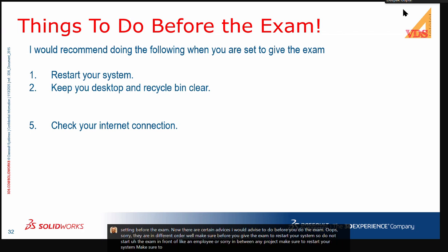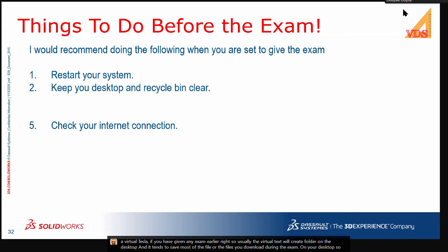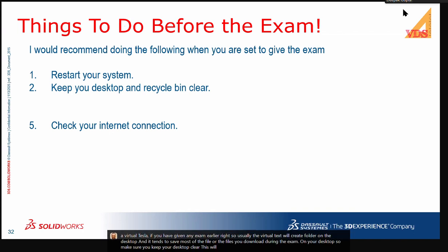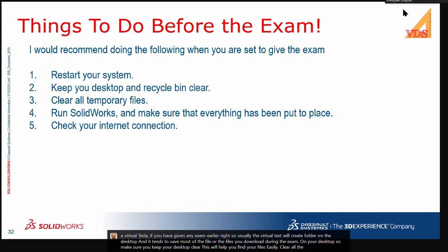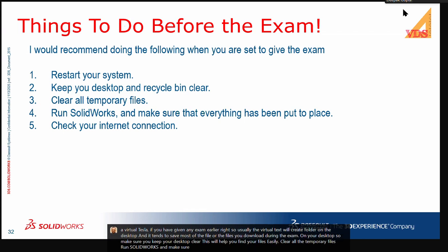Make sure to clean your desktop and the recycle bin. When you do a virtual tester, if you have given any exam earlier, usually the virtual tester will create a folder on the desktop, and it tends to save most of the files you download during the exam on your desktop. So make sure you keep your desktop clear. This will help you find your files easily. Clear all the temporary files, run SolidWorks, and make sure everything has been put in place, which means the command manager and the shortcut keys. Do a quick model to check the shortcuts and everything is working.